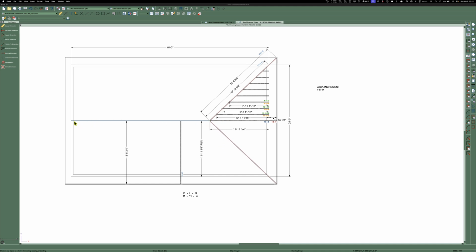And then if I have a close layout over here, I don't really care. Because I'm just going to stick it out there and either pop a line and cut it off up there, or have whoever's on the ground cut it. And now with track saws, man, guys can cut some really nice stuff. You can even bevel cut your plywood to go up on your beveled hips and just make it awesome.